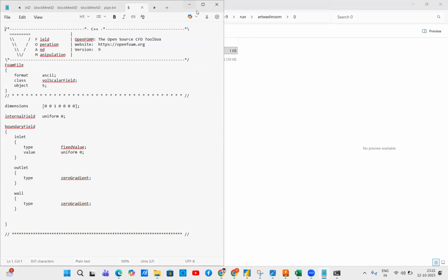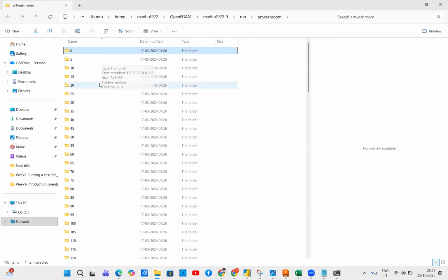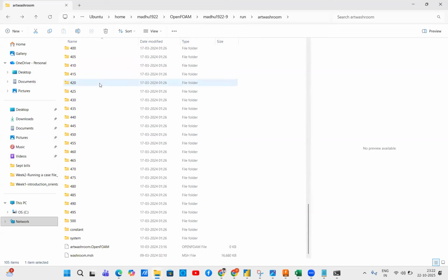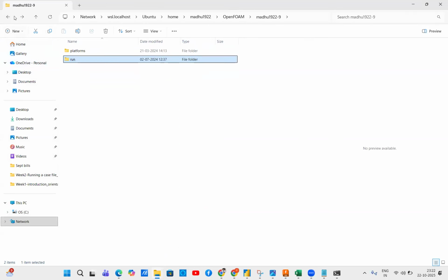For creating this one, we have to make certain changes to one of the solvers which we currently have. For that, we have to go to the solvers in the tutorials, copy one tutorial, change certain things, and implement certain headers and bashrc files to create a solver to calculate anything.